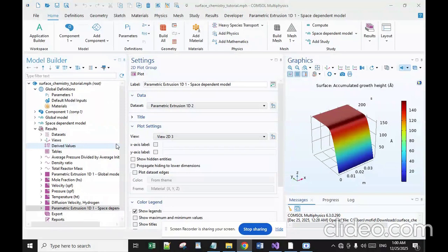Silicon nitride. Silicon nitride is often used as an insulator and chemical barrier in manufacturing ICs. The following two reactions deposit silicon nitride from the gas phase. Silicon nitride deposited by LPCVD contains up to 8% hydrogen. It also experiences strong tensile stress, which may crack films thicker than 200 nanometers.